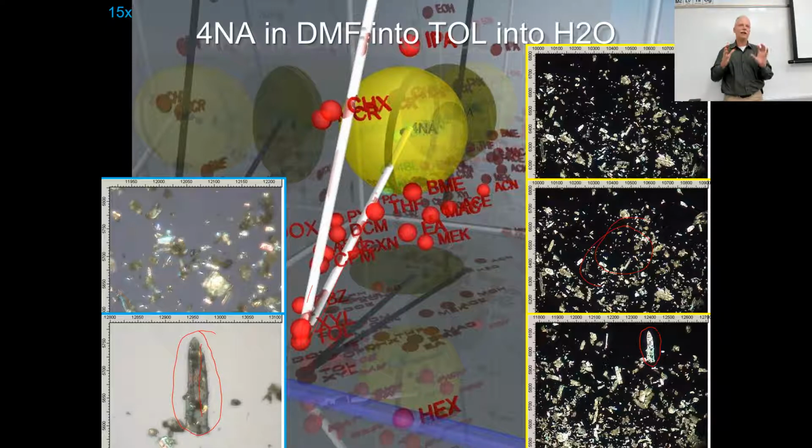This tank just doesn't do right for the first 6 months, but after a while, it really gets good. What's going on? Well, you probably have some scale building up around the heating elements, and now it's working because that scale's helping your yield. Like that container in the old facility, it had a copper surface, and that made all the difference in its crystal morphology.